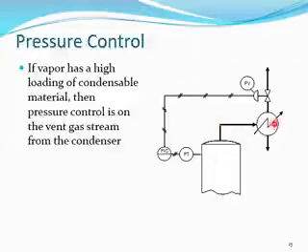So when we condense, the pressure goes down. That's why we need to control the pressure of the vapor coming out of the condenser. If the pressure goes up, we can open here or increase the coolant, so more condensation happens and the pressure drops, and vice versa.